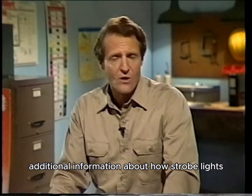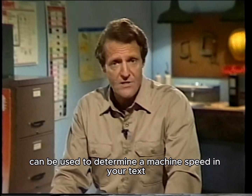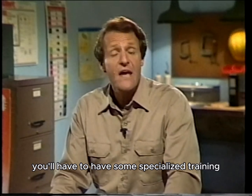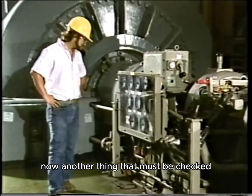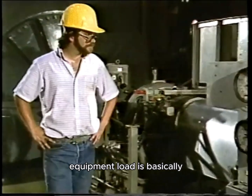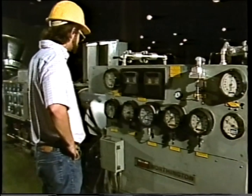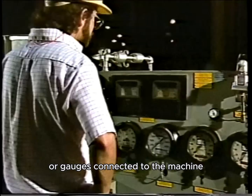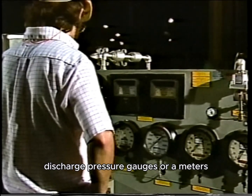You'll find some additional information about how strobe lights can be used to determine a machine's speed in your text. But to really understand what you're doing when you use a strobe light, you'll have to have some specialized training and practice. Now, another thing that must be checked and matched against the baseline data is equipment load. Equipment load is basically the amount of work that's being done by the machine being monitored. Equipment load is normally checked by looking at meters or gauges connected to the machine. These may be flow rate gauges, discharge pressure gauges, or ammeters.